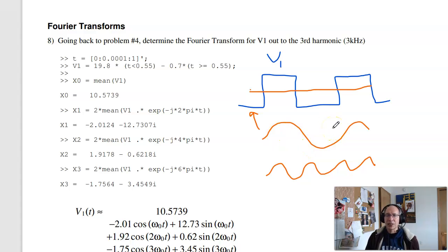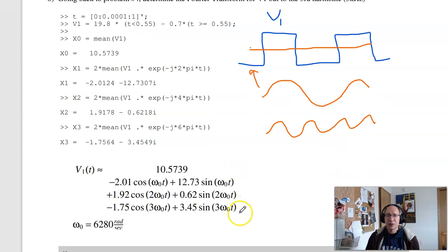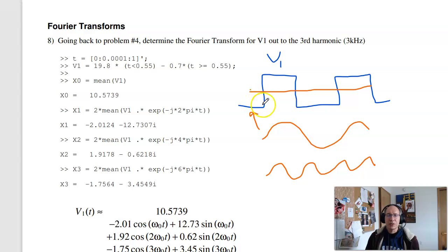That's phasor analysis. So what I'm going to do is take this problem and use Fourier transforms, something you're going to cover in 343 Signals and Systems, and find the spectral content of it. Then analyze each circuit with a separate input using superposition to find the output. So first off, find the Fourier transform of V1.